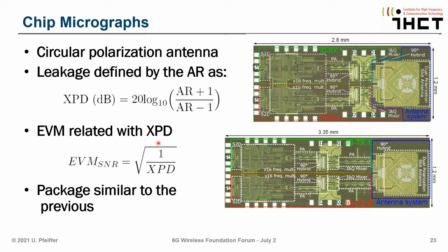And now the question is, how much crosstalk is related to this implementation. And there can be crosstalk, of course, directly on the chip, but also through these hybrids. There can be some signals of this red transmitter can actually make it over to the green receiver on the other side if there is, for instance, some imperfection.